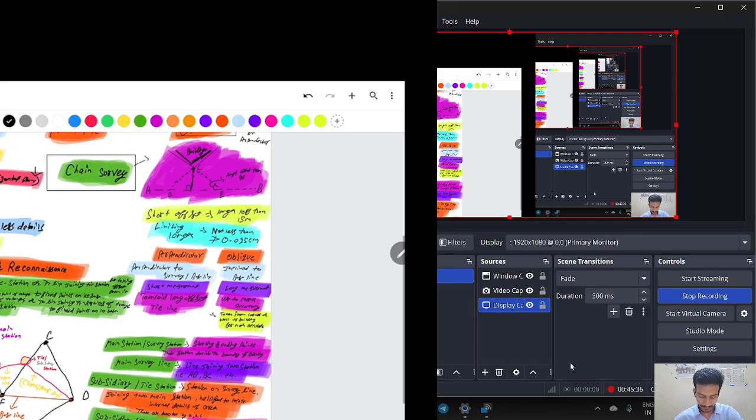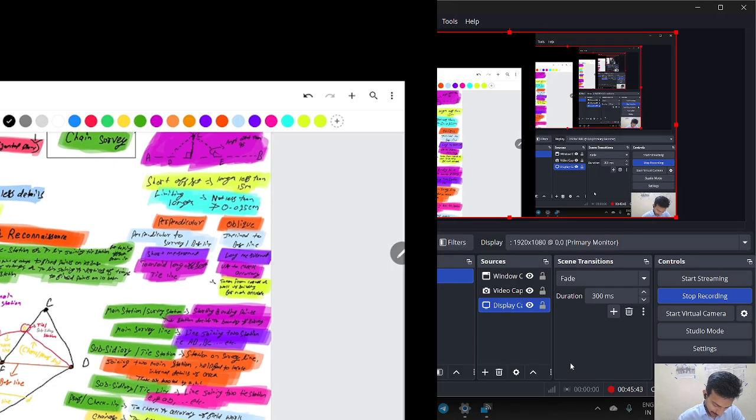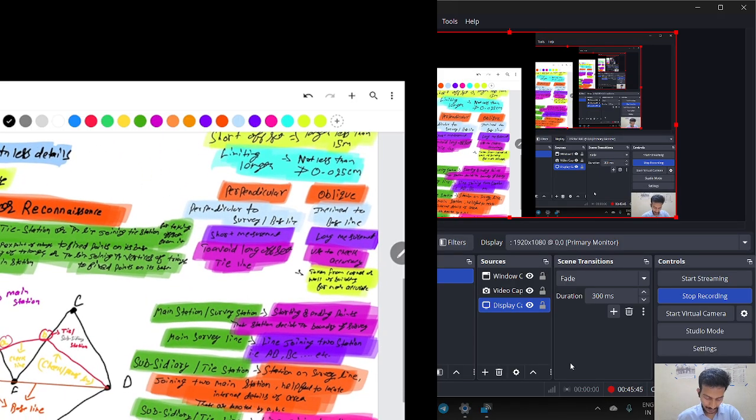The reference sketch or index is drawn. Tie line, this is important: the line joining tie stations, for taking offsets from it. Check line: the line joining the apex point of a triangle to a fixed point on its base, to check accuracy of the triangle, or the line joining the vertices of a triangle.